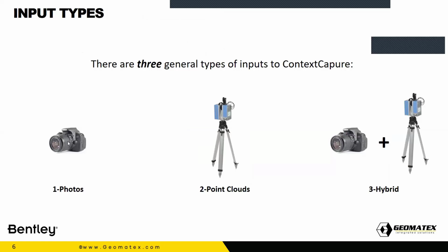You know, one of the common mistakes is that reality modeling or this technology is just plugged into drones or aerial platforms, because you can use your normal camera or even your laser scanner, because we still have a hybrid mode in which you can merge both accuracies: spatial accuracy from the imaging and point cloud accuracy from the laser scanner. But you still could use ground tools to acquire a very, very accurate and maybe more accurate model than from an aerial perspective.